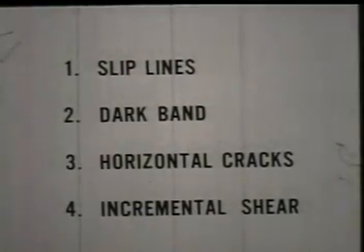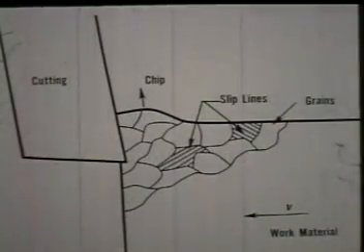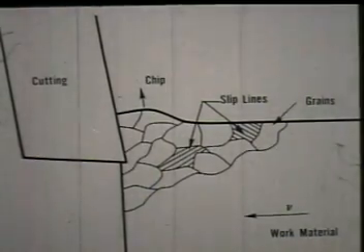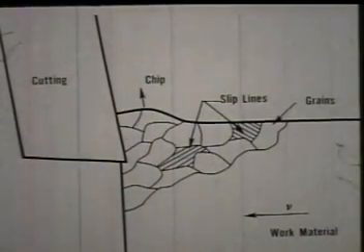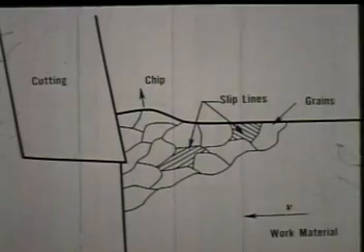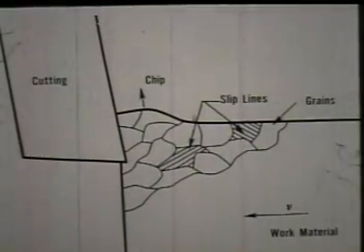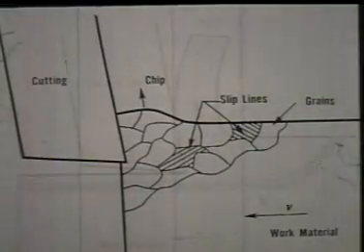inclined plane. When cutting commences in 1020 steel, slip lines form in some ferrite grains several grain diameters ahead of the tool. Slip lines form on the surface of a polished grain during the first stages of plastic deformation. As the cutting proceeds, slip lines continue to form a considerable distance ahead of the tool.